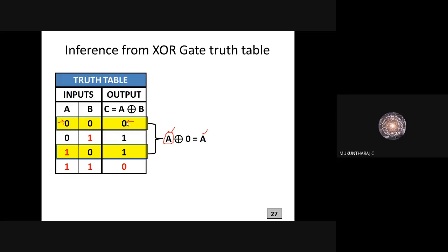Same value, same result is applied in the output of the XOR gate, right? So this can be cleared in this case. Here the logic input A having logic 1 is XORed with logic 0, which is assigned to input B. This combination produces logic 1. So this logic 1 is available on the input variable A. So these two outputs are nothing but the input A.